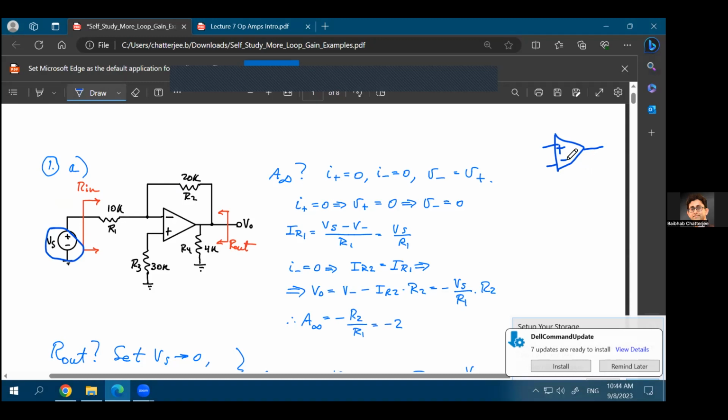And that's what gain means. You have an input between these 2 terminals, and your output will be the gain of the op-amp times the difference of the 2 inputs. But whenever you have the op-amp in these configurations where there are additional resistances, and there could be, for example, capacitances or inductances as well, if you just want to make the circuit more complex. But in this course, we'll mostly deal with resistances. So don't worry about those more complex configurations.